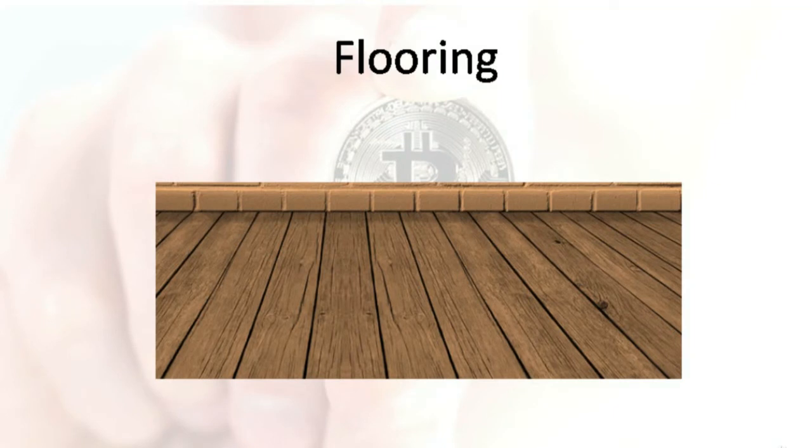Of course, the other option is the hard floor. This simply means that all of your equipment is placed on just concrete slabs. With this option, there are two advantages: it is cheaper and it's less susceptible to damage. As for the disadvantages, it is mainly that all the cooling and cabling will need to be fed overhead through ductwork. And if you need to reconfigure ductwork, for instance in rerouting cables, it is actually much harder to modify ductwork than pulling just a few tiles underneath.